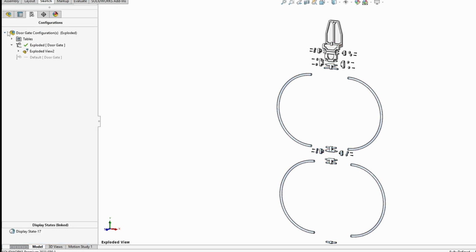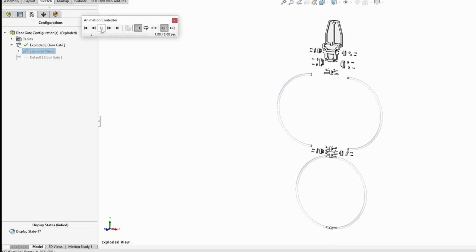Before we switch to the sub-assembly, let's check the animation. Maybe there is something there that is wrong which we also need to change in the sub-assembly. So if we animate the collapse, I'll just pause right away. Then I take this little slider and move it back, and then I can control the steps. You can see if I go up here, we have the left ring, then the right, and then move up and down, and then we have the right, and then the left. So when we come over to the sub-assembly, we need to move the steps around, because I want the left part moving before the right part for both rings. It will look nicer if they are in sync.